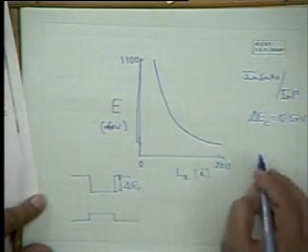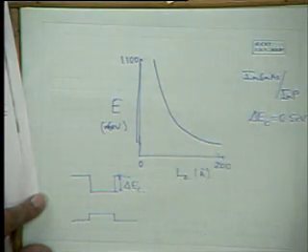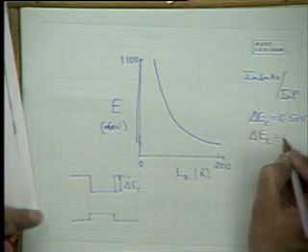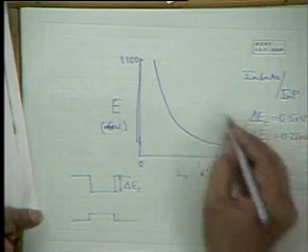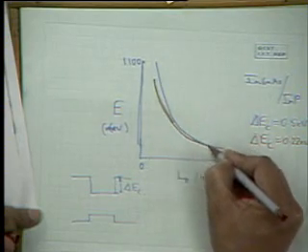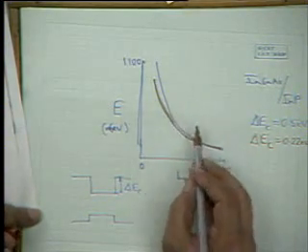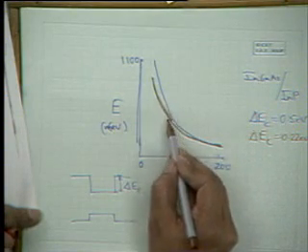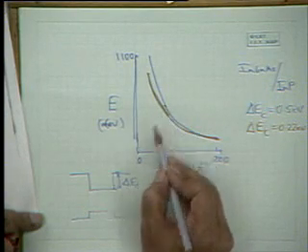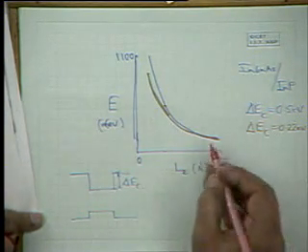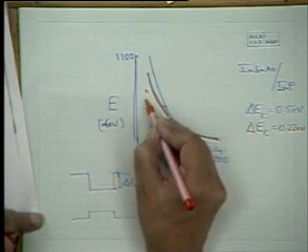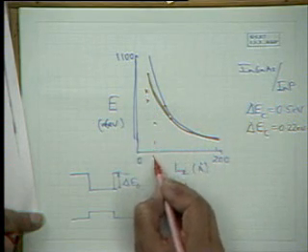And if delta EC is 0.22 eV, which is more realistic for this system, then you get a variation of this type. So if the barrier height is higher, then for a particular value of LZ you will have higher confinement, higher energy. And experimentally, what does it compare with? Experimentally, this is Razeghi's data. You have one point here, but the other points are way off. There's about a 50 angstrom well.